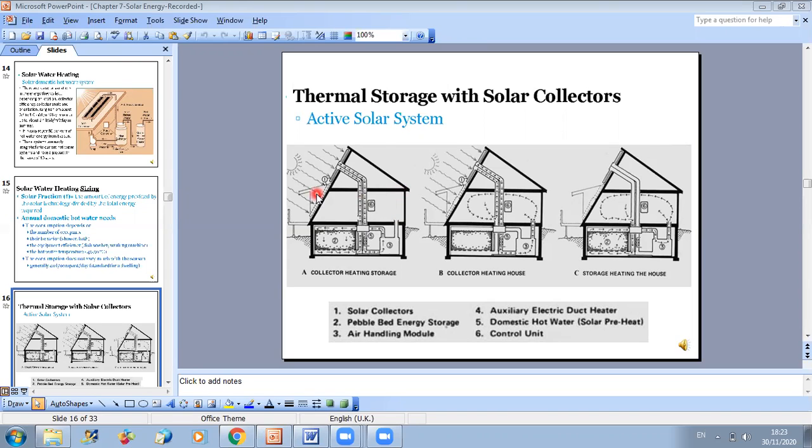It's relatively warm already. So the energy collected from the sun will be transported through the fluid, and this fluid will go over the thermal storage material. The thermal storage material will extract energy from the fluid and store it to deliver when needed. So here, no heat is transmitted to the space because the temperature of the space is relatively good.